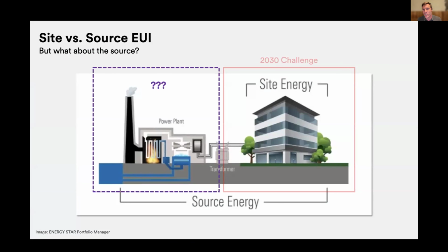And this has started a debate that has run from then till now about how to think about site energy metrics versus source energy metrics, and whether the narrow focus on the building site isn't maybe the only thing we should be considering. I'm going to leave aside the difference between site EUI and source EUI, mostly because when it comes to carbon analysis of buildings, source energy use isn't really treated very closely.